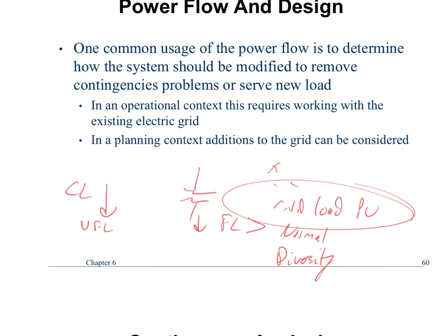But back in the day, stuff was built so much like a tank. If you walked around this facility, they had 1,000 MCM ground wire. I've never seen anything like it. Usually you see 250, 500, 1,000 MCM everywhere. They had 750 MVA rated 13.8 kV gear. At the time, that was still the highest rated equipment you could buy. Everything was gold plated. It was just the best of the best, and so it was a tank.